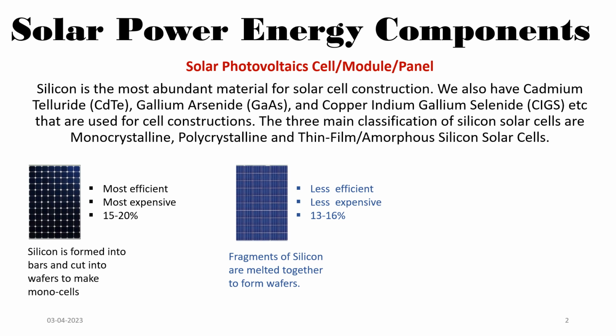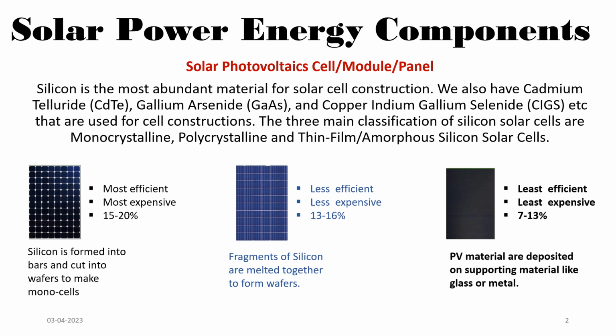The efficiency lies between say 13 to 16%. So it's the mode of construction that differs from the monocrystalline. Then we have the other one, that is the amorphous one. And this amorphous one, the thin film, some call it, they are flexible.